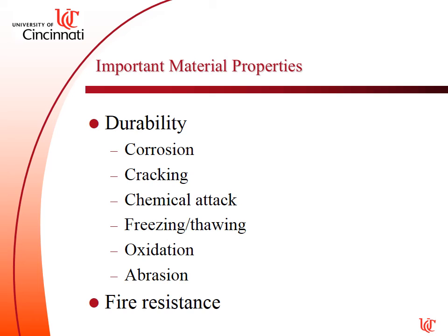Are we going to spray something on it? How does concrete perform? How does wood perform? These are all things that might dictate you going a different way in a design, not because it was a strength property, but because it was something like fire or corrosion.